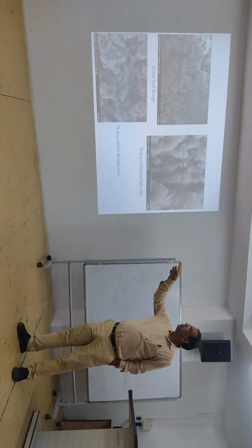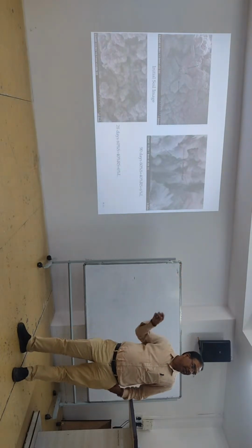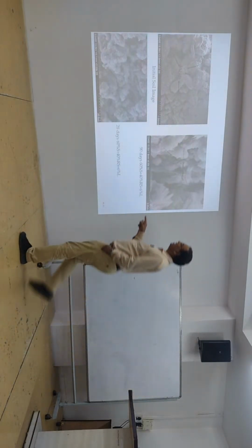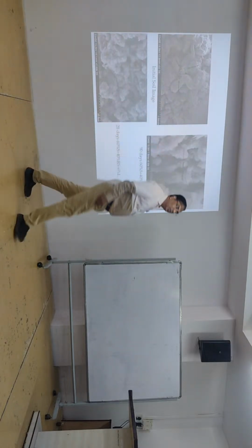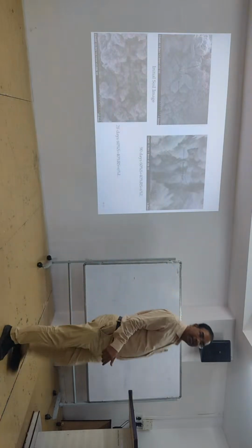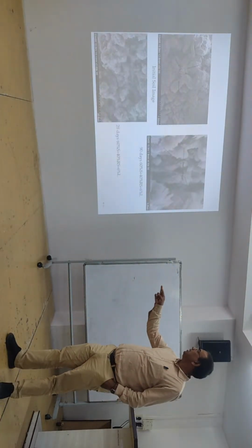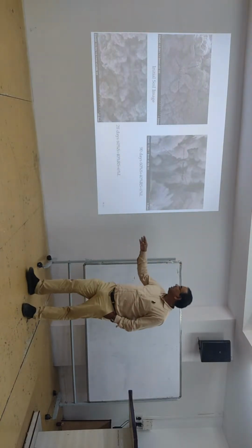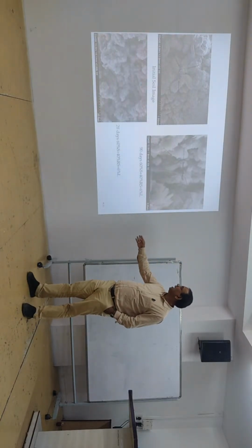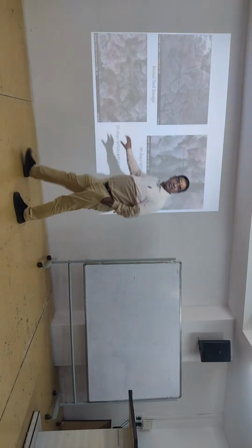In some soil images you can see very different, broken aspects. That's why we get black cotton soil like that. And at 28 days you can see your soil with 40% recycled sand and lime. You can see gel is forming here.